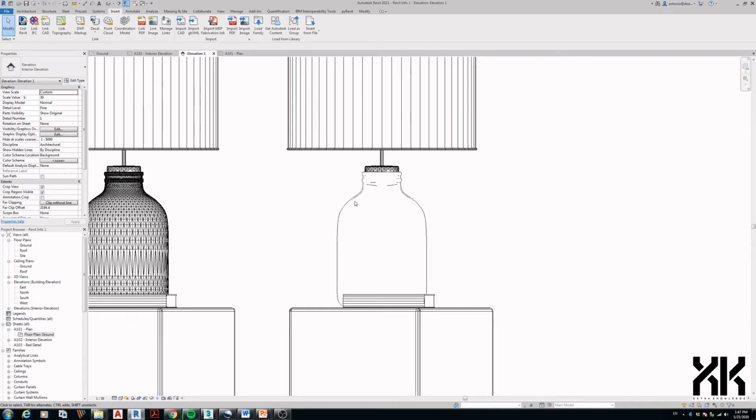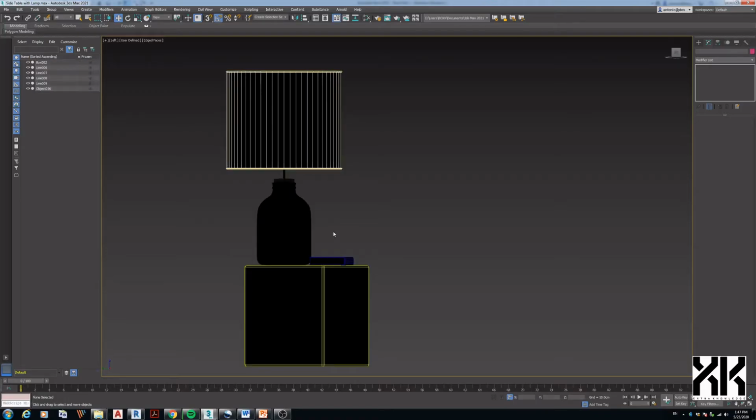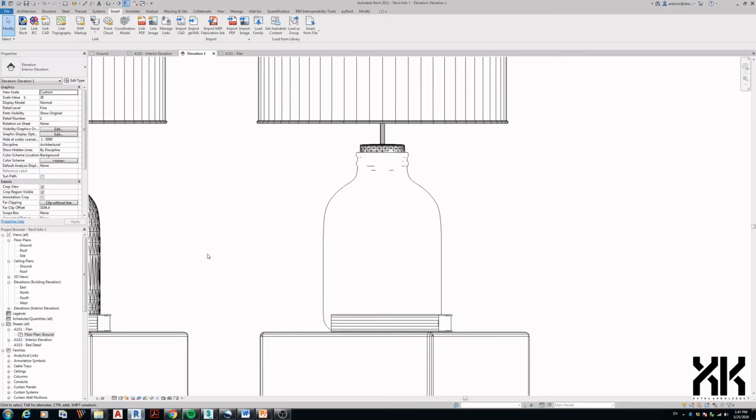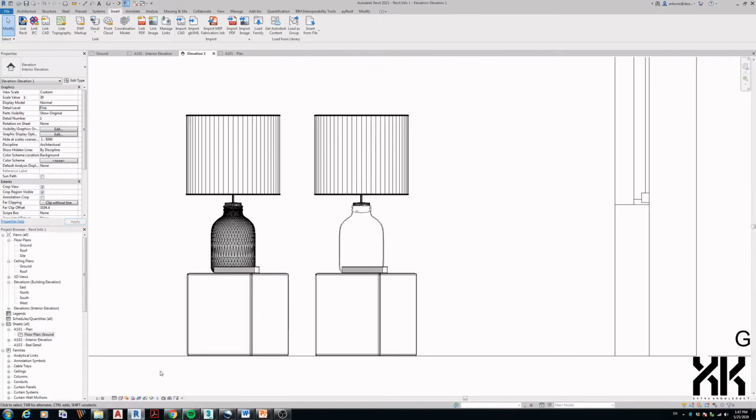The model is now acceptable for drafting, but we can still change the object definition if we want to. By doing this, we can set the detail level of the object. Let me show you the detail level list in Revit. In View Property panel, select the detail level. As you can see, we have three options: coarse, medium, and fine. We can see this also under View Control bar.